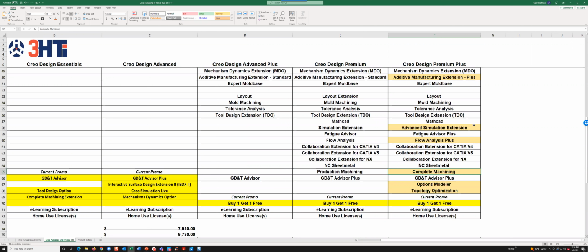Closing the loop really comes to you have the as-designed and you have the as-manufactured part. What they're trying to do is that you really need to specify the GD&T up front. So ultimately, as quality gets involved, which many times is where the as-manufactured part comes in, you have those tolerances in line with the geometric dimensioning and tolerancing.